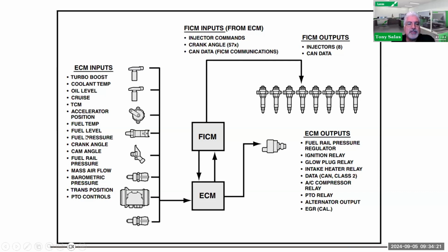Even something as frivolous as fuel level input is important, because if you're familiar with regeneration, regenerations will not run if the fuel level is too high, too full, or too empty. What about the brake switch input, the brake on/off input? The brake switch can also cause no regenerations to run, so that's another very critical one. It's not even listed here, by the way, but it is important to have brake pedal input.